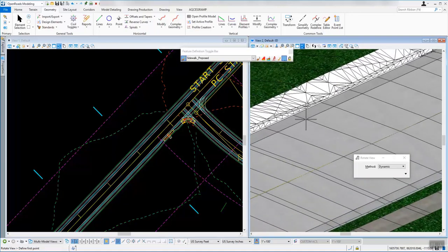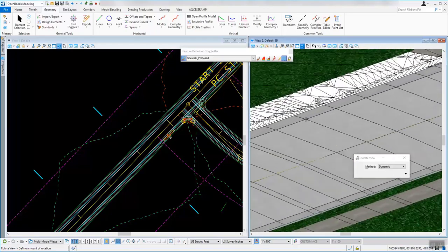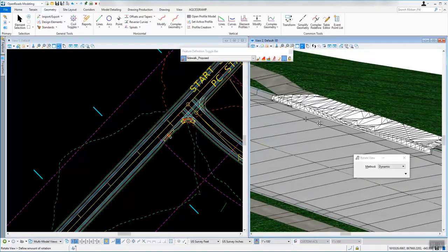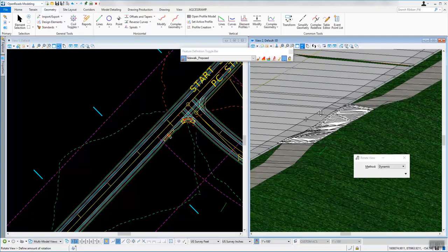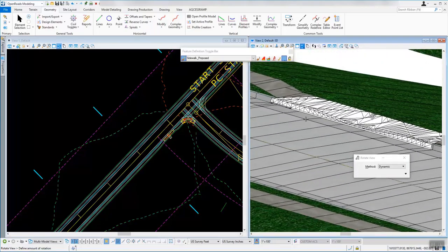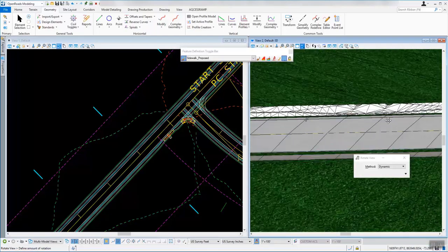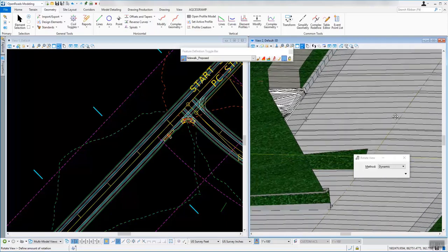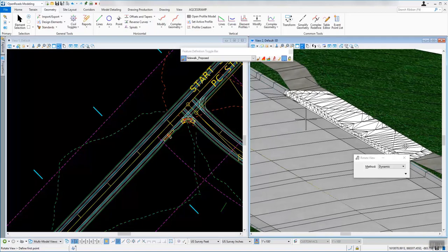and brought in the curb, slid it down. Now we've got that opening right there. As you can see, it's gone back up and met the sidewalk on either side. So it's not too bad. It's got a few glitches here and there still every once in a while. You can see in the surface back there, it kind of changes up a little bit. But we can make modifications to that. It would be a short little modification. It's really easy to create the curb ramp and then just go modify the surface a little bit if you need to. So you can see that would save you a lot of time trying to create this model by hand.